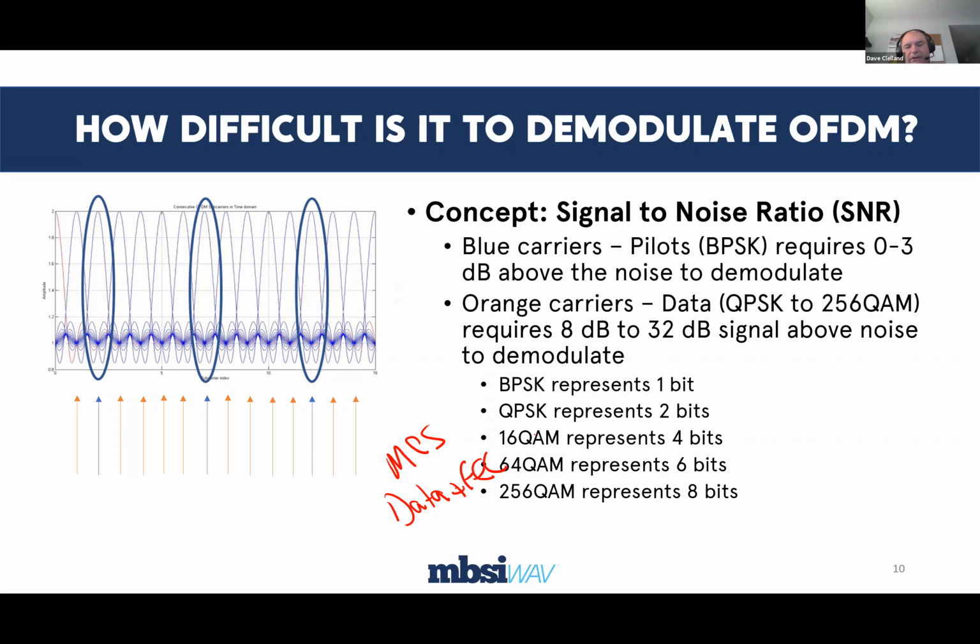So it might be 2 bits or 3 bits or 1 bit, depending, of the bits represented by the symbol that are actually forward error correction, and so the system can mathematically correct its errors when it knows what the forward error correction value is for each symbol. If the signal to noise ratio is not quite high enough, but it knows what the FEC is, it can mathematically make that judgment as to what the value in that symbol actually is.